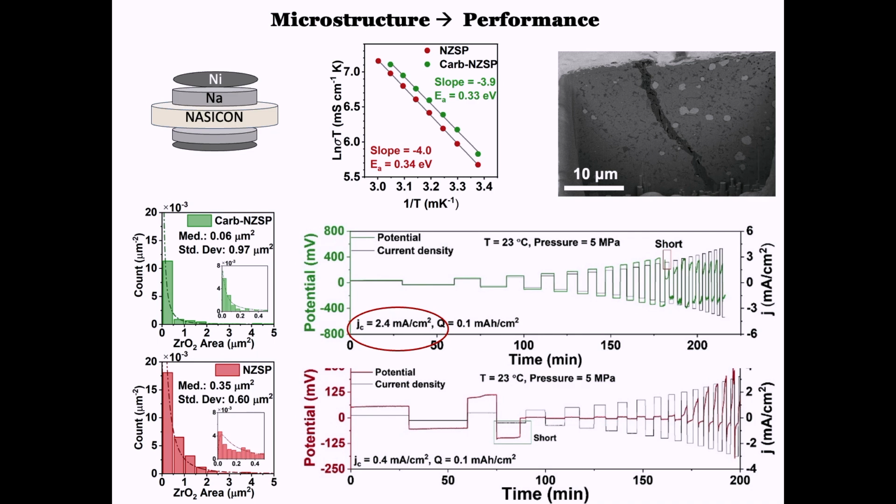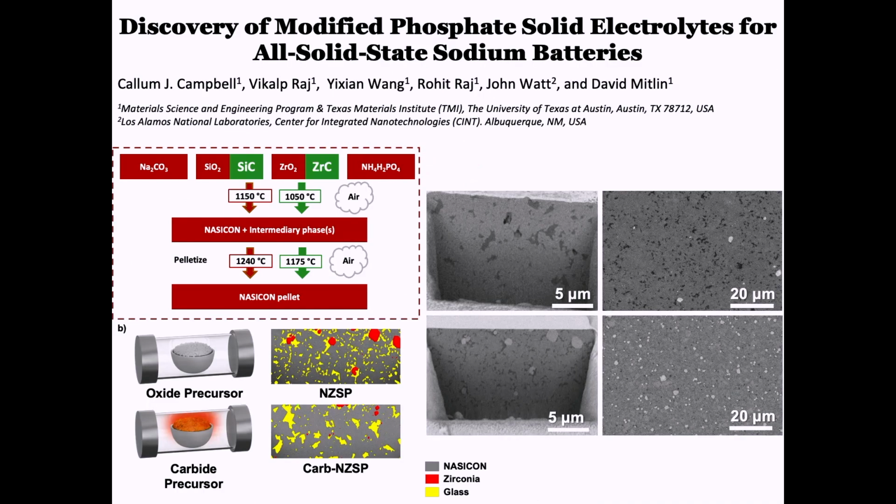So in a great collaboration at the user facility out at SINT Sandia, we did cryogenic microscopy using a FIB-SEM to take a few of these images. And we're basically, at this stage, trying to understand the fracture mechanics, which is really the issue with these ceramic materials. We're trying to understand how do these metal filaments push their way through, open the cracks, and why does one microstructure, I'll jump back, why does one microstructure like this behave in a different manner than the traditional microstructure you might end up with?